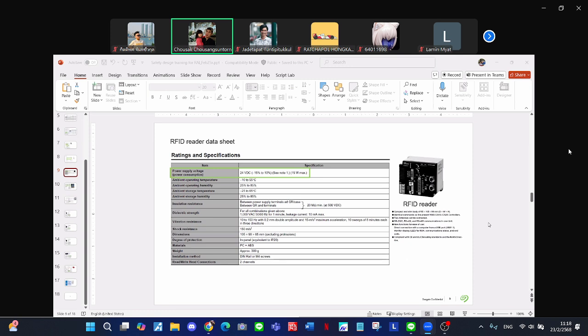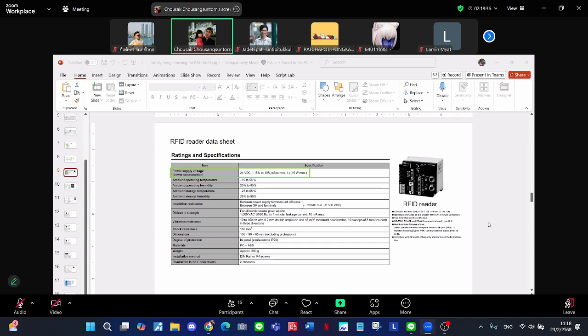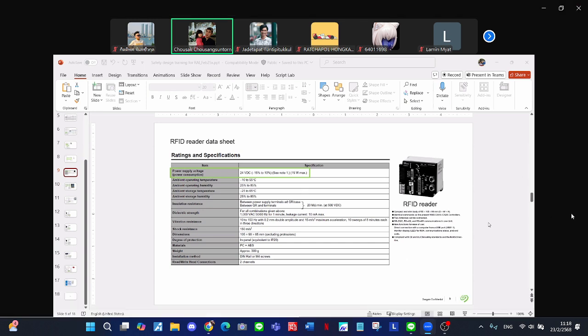And when it's multiplied by the 25% safety factor, it is this value, right? We choose the closest circuit breaker rate from the standard ones. It has 0.5 and 1 ampere like this. For me, I consider 1 ampere to use. Okay. And we will use this value to select the wire size again.